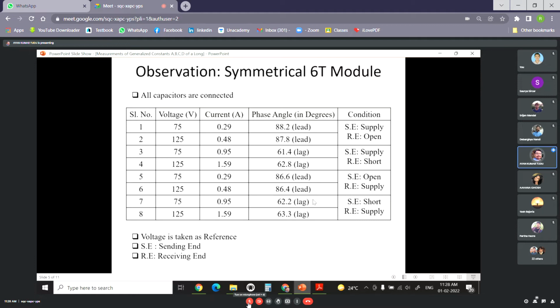While series reactors are used for limiting the fault current, shunt reactors are used for reactive power control. As I said, whenever we have a lightly loaded condition in the transmission line circuit, shunt reactors are connected so that they absorb the reactive power from the system, so that the voltage goes down to its nominal value.